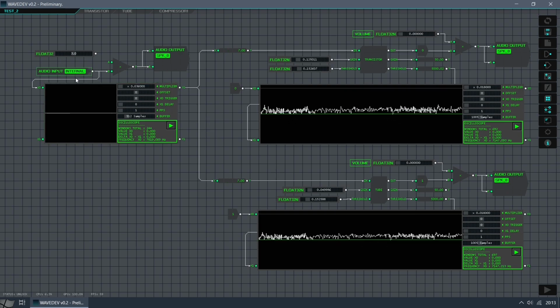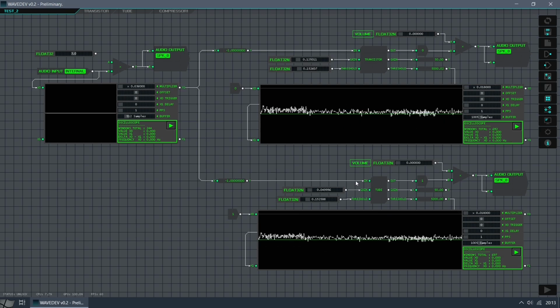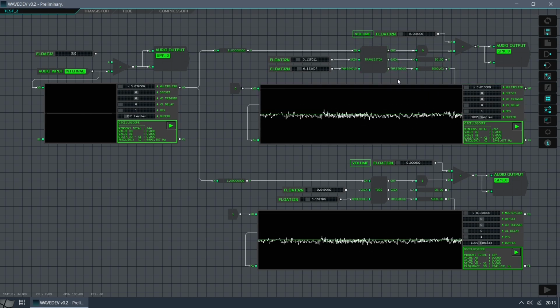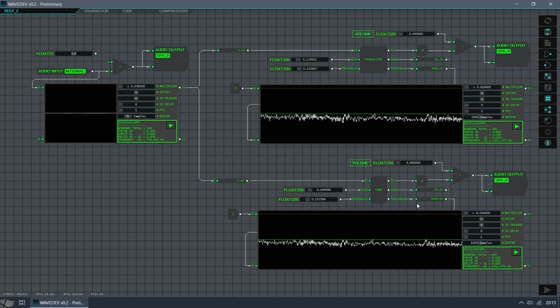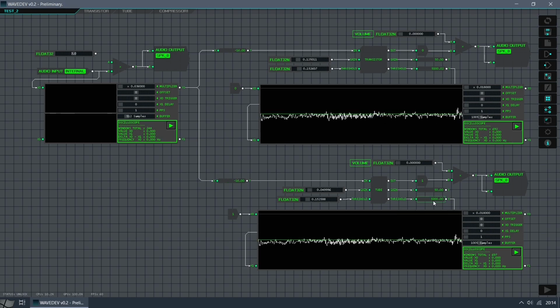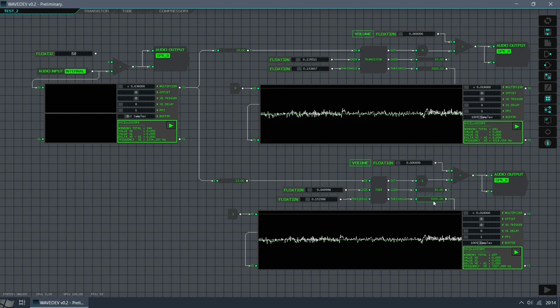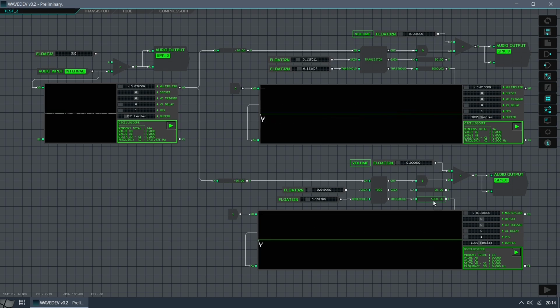I'm going to send the guitar signal straight to these blocks to know what they actually do to the signal. I set both amplifiers with the same parameters. I chose a threshold of 5000 for the clipping, and will keep it fixed from now on. We will work with values in terms of conversion, so the limit for all variables is around 32,000.